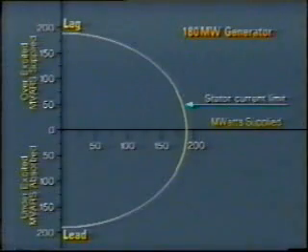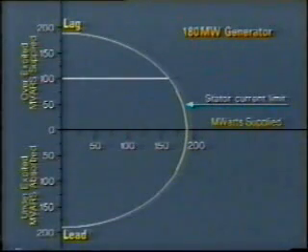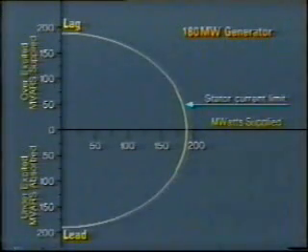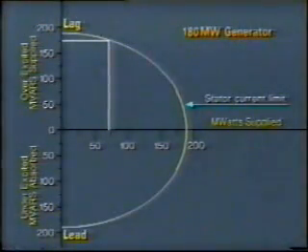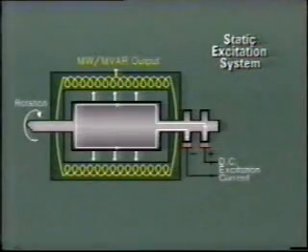This curve shows us the limitation of MVA due to current in the stator. For example, at this megavar loading, we can only produce this amount of megawatts to stay within the machine's capability. Clearly, in order to keep within the MVA rating, we must reduce megawatt output if we wish to produce a large output of VARs on the generator. However, there are other limits to observe in generator operation.